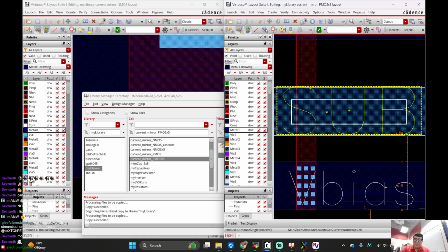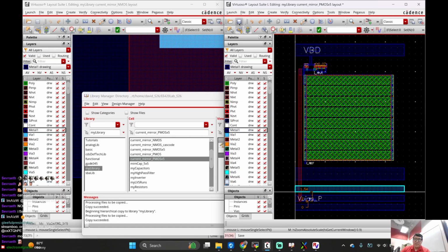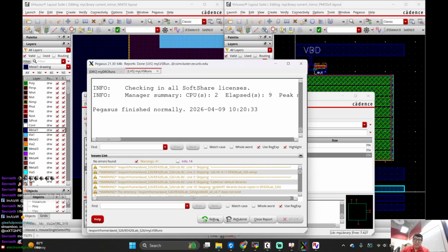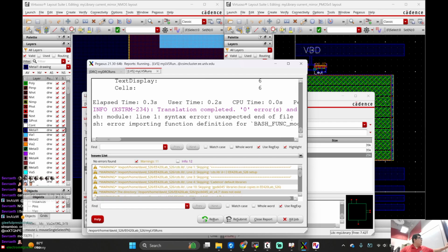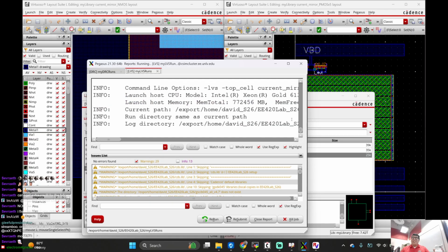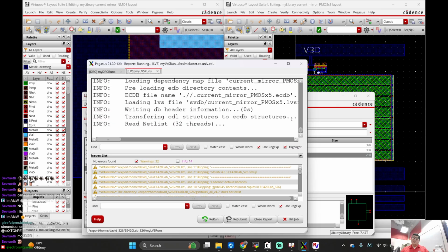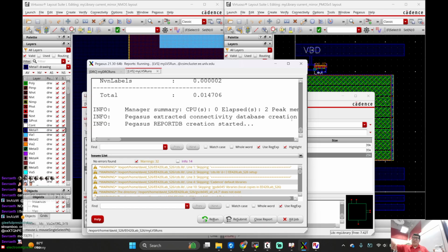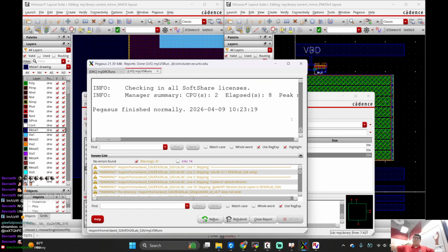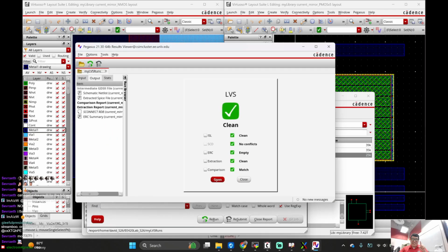Let's get rid of this, because we don't have a sub in here. So let me just LVS it again. This, I think, should fix the problem. Basically, it's saying it exists in the layout, but it doesn't exist in the schematic. And that's true, because we drew a metal 1, and it exists. Sub, the pin is connected to a metal. Let's see if my philosophy is working. Oh, yeah, baby. Let's go.